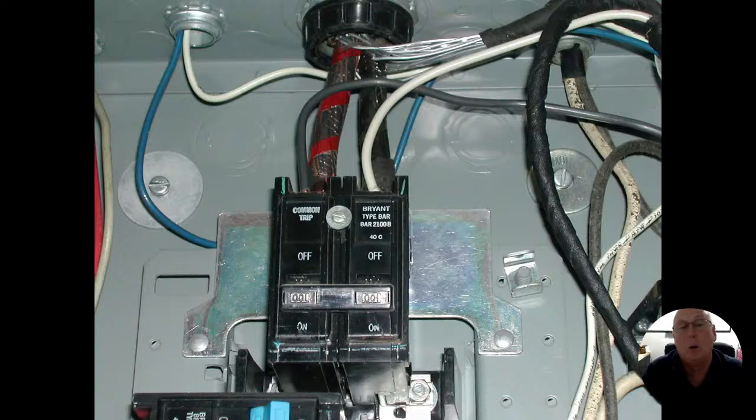Those breakers will allow up to 100 amps to flow, whether they're flowing at 120 volts or 240 volts, doesn't necessarily matter. It's going to allow 100 amps to flow. The problem now comes in with that black and white wire that's tied in off the top of this. Those wires also are only designed to carry 100 amps. We don't know what they're hooked up to, but let's say they're hooked up to something that's going to allow 50 amps to flow. Now I'm going to be able to allow up to 150 amps to flow down those wires that are only designed to carry 100 amps.